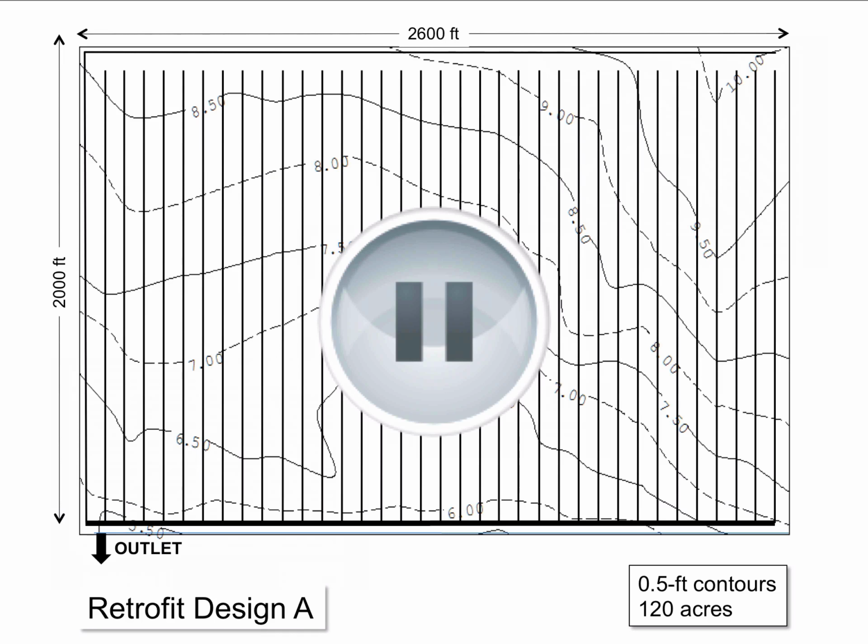So you could use an elevation interval of 1.5 feet if you'd like, or you could use 2 feet if you'd like. So you decide where you'd like to place your structures and then delineate the zones that are going to be influenced by those structures given the elevation interval of your choice. Go ahead and take a few minutes to do that, and then I'm going to sketch out a couple of possibilities here to continue.